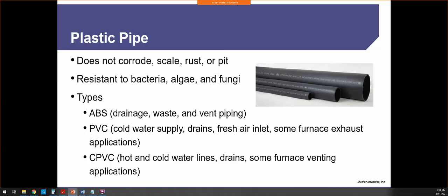and so the international mechanical bodies that govern all the mechanical codes for us, they're really starting to say that we should go to polypropylene. It's got a much higher temperature resistance before it breaks down. It's closer to the 200 degree range, and so we may start to see changes. If you have polypropylene, awesome. You know, there's nothing wrong with that. PVC, we have to be careful that our system isn't running too hot and having issues.